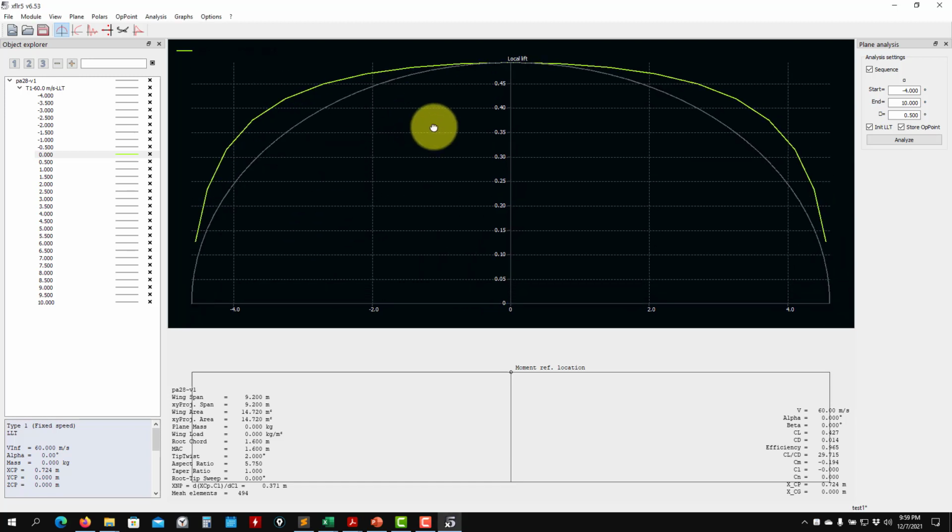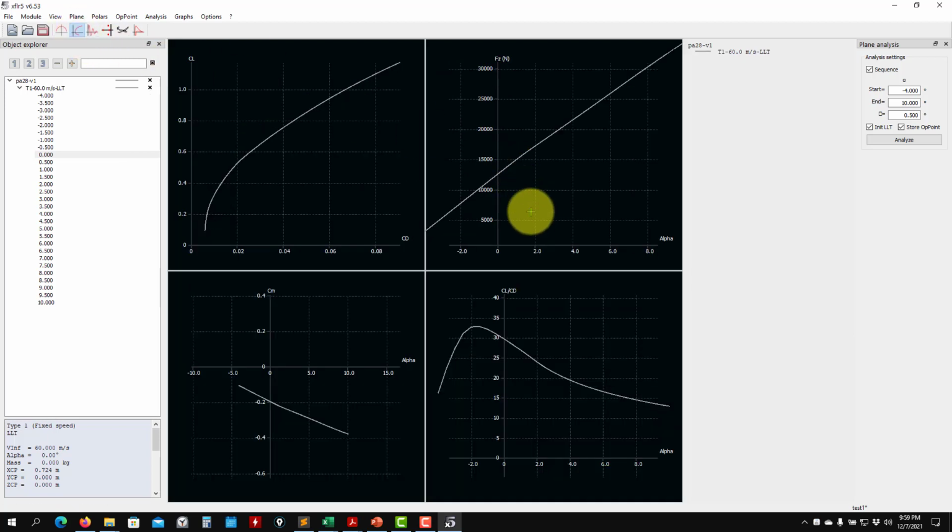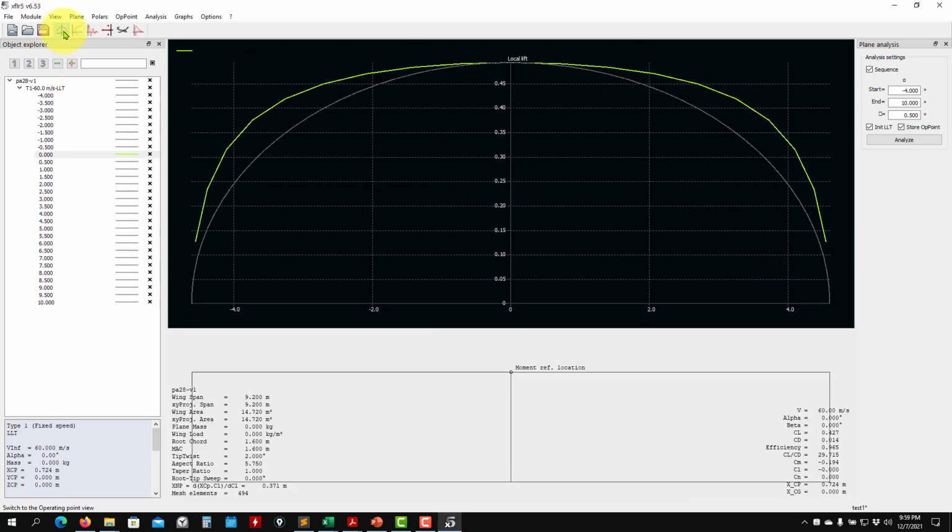And this is it. So our idea when designing the wing, we already know that we're producing the required lift. There is no problem, there is no deal there. The problem now is that we want to do things in an efficient way. We want to reduce the induced drag component, and to reduce that one we need to get closer to this elliptical lift distribution.